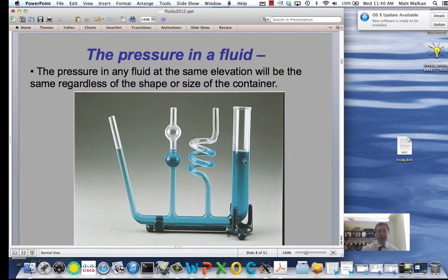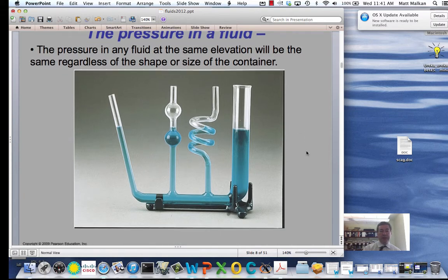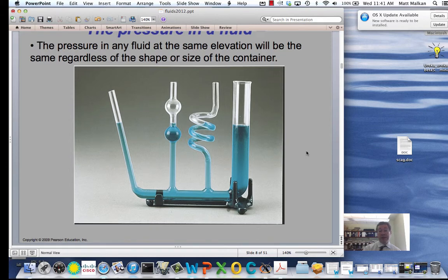The blue fluid were down here. Then the pressure of these other columns of fluid would push it back up and they would lower down. So they all have to come into equilibrium here. That's what hydrostatic equilibrium means. So that's why all of these levels have to be at the same height. That might help you solve some problems where we have a complicated geometry, because this is a very simple thing that they have in common.